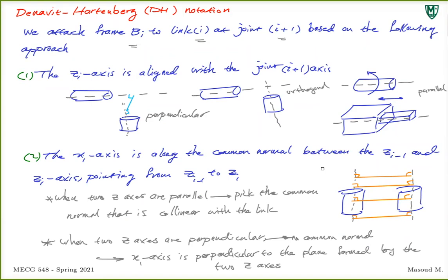But this gives us a standard approach. So anyone who looks at a robot arm or serial link manipulator should, at least to some good degree, come up with the same set of frames and get the same kind of transformation matrix. Now, this is the base. We'll learn how to put the frames. Once we learn how to put the frames on a serial link manipulator, we look into how we can find the transformation matrix between those two frames using this specific notation.